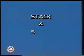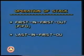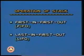The stack and stack pointer is used to save this information. The contents of the stack are the information to be saved, and the stack pointer points to the location where the information is stored. The stack is an array of registers and may be organized either as first in, first out, FIFO, or as a last in, first out, LIFO manner.